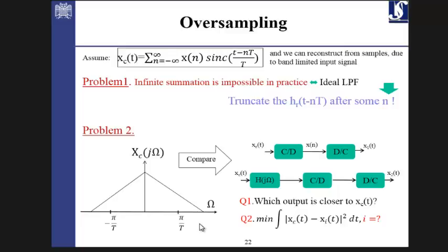We cut it down. Even if it has some information, we ignore it. It's much better to ignore that information in the beginning than leave it with the signal until the end to face it again. Because if you do that in the beginning, you will just lose this part of the information. But if you forget about that filtering here, then in the process, where it becomes periodic, you have patterns coming from the other sides, and it actually goes through the other side of the information, and it screws up even more information of the signal in the frequency domain.